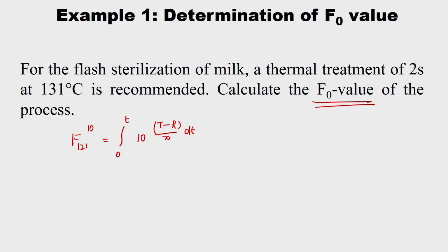So, they told that the thermal treatment took 131 degree centigrade for 2 seconds. So, what should be its F naught value, right?